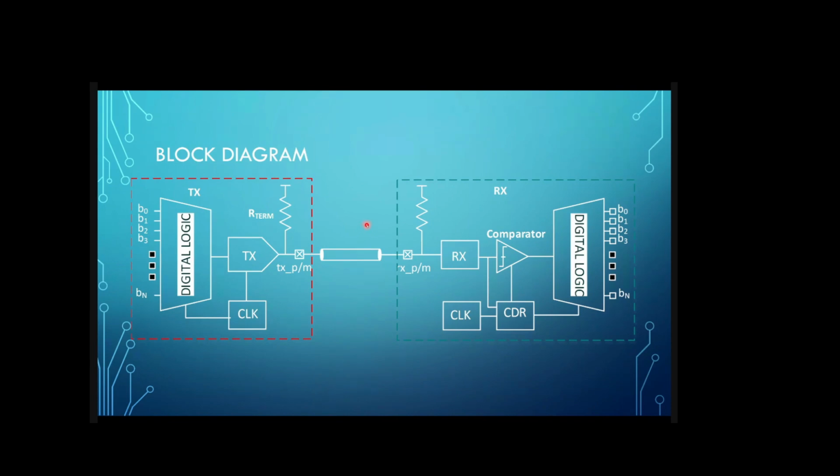Coaxial cables usually have 75 ohms, which is coming from the outside there. So 75 ohms. Usually TVs also have 75 ohms too. Okay, 50 ohm is usually for different data transmissions as well, or from the lab and other places too. So you need to terminate them. You may have heard about this termination part.